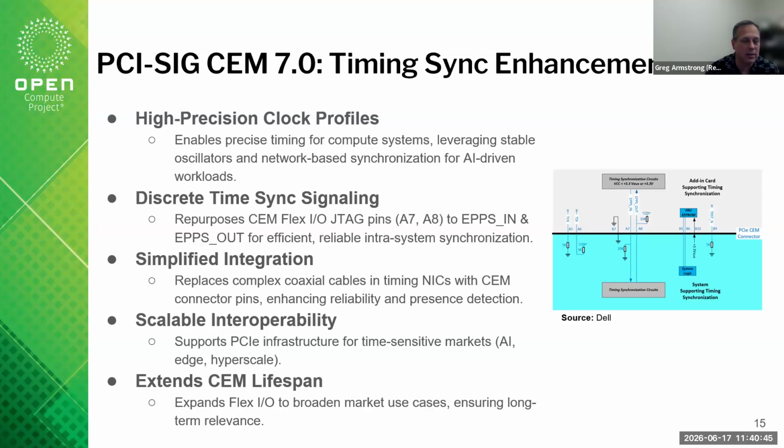So you create the ability to do clock distribution, and to put timing into cards. The time card could be a plug-in card now. It could be coming off a NIC that supports synchronous Ethernet, PTP, or even White Rabbit, getting that clock in and pushing it into the system. And you can create redundancies.